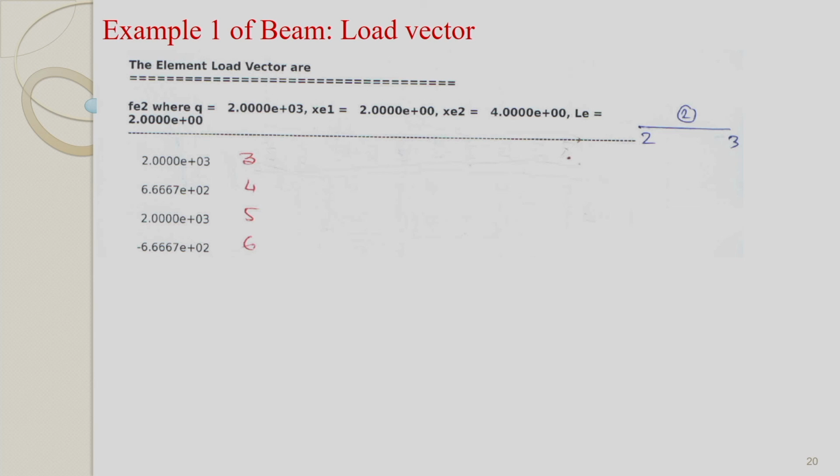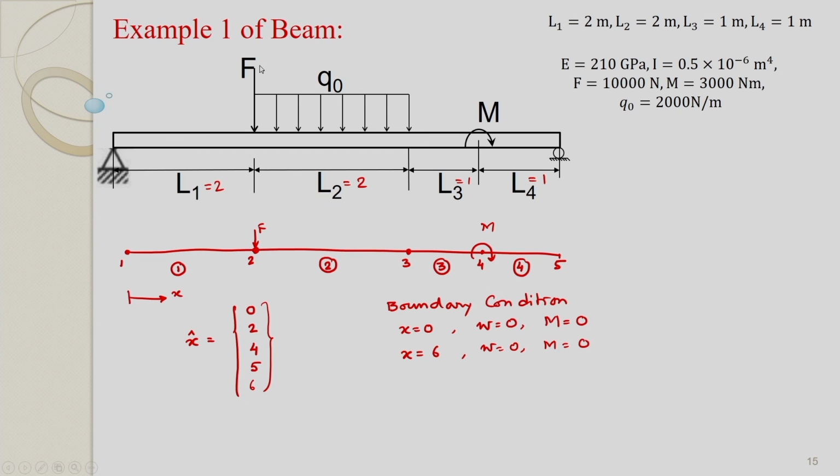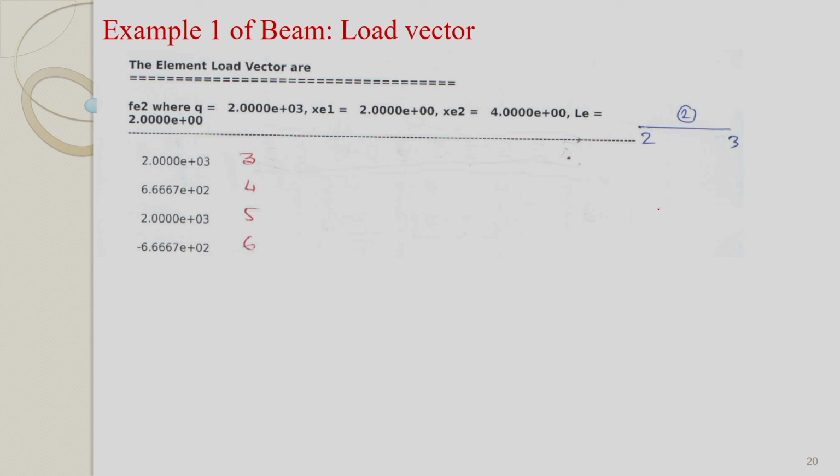For this problem, there are also a point load F and moment M at node 2 and node 4. So, point load is associated with the deflection degree of freedom. So, node 2, that point load will be acting at DOF 3.